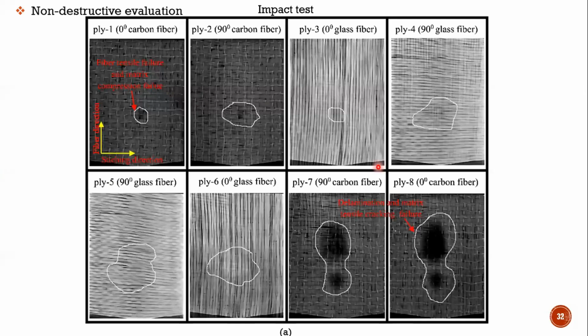So what we can do is go for non-destructive evaluation using X-ray CT scans. Here we know the thickness of each lamina. Then we do X-ray scanning of that particular laminate for different thicknesses, and we generate surfaces throughout the entire thickness of the specimen. Those surfaces are generated at the lamina thickness, and then we get to know the different failure modes happening in that laminate.